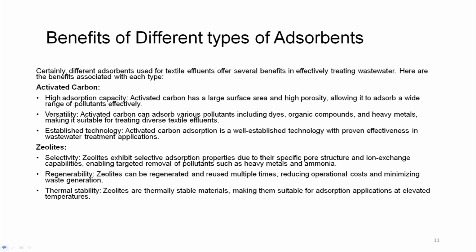Zeolites. Selectivity. Zeolites exhibit selective adsorption properties due to their specific pore structure and ion exchange capabilities, enabling targeted removal of pollutants such as heavy metals and ammonia. Regenerability.